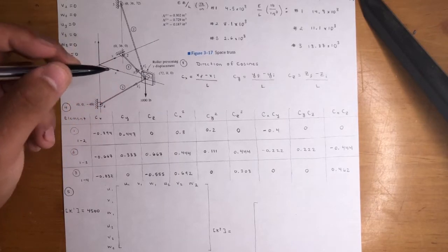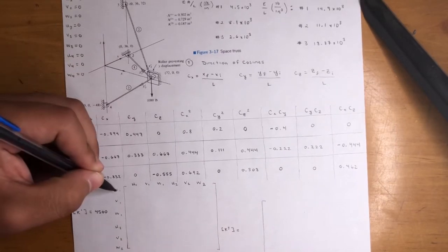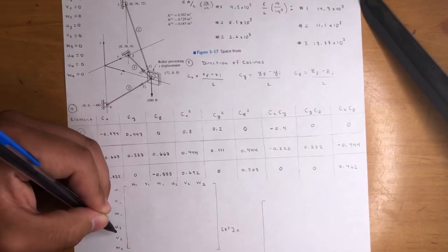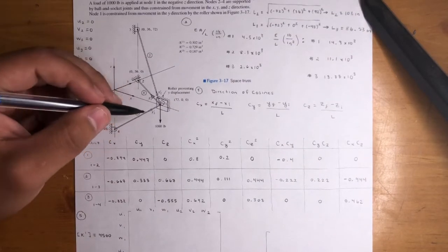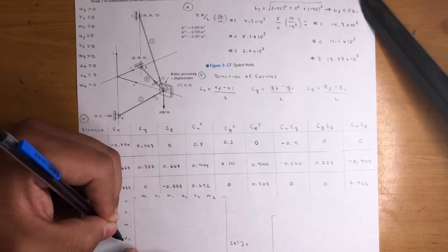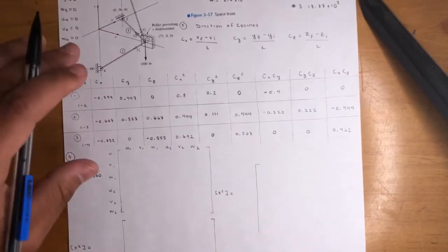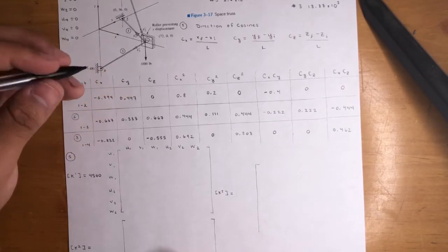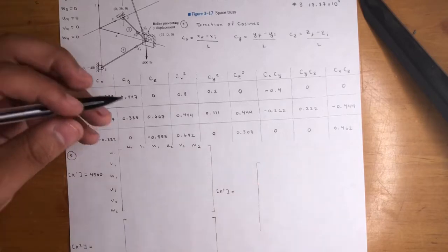be consistent. So if you went from 1 to 2 like we did, we're going to go U1 V1 W1, U2 V2 W2. If you would have gone from 2 to 1, you would have had U2 V2 W2, U1 V1 W1. They would have just switched. But you have to understand that that's really important, okay? So cool, we'll keep that for now. Hold on, I don't want to fill it in just yet.